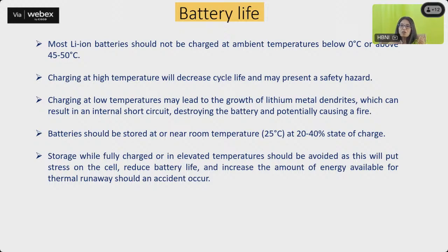Gradually, because of the degradation mechanisms which happen in even the best of batteries, it will start losing its capacity over time. And when it reaches 80% of the capacity, that is, no matter how long you charge and discharge it, it is not going beyond 80% of the capacity which it was initially showing, that means you have reached the end of life of that particular battery.